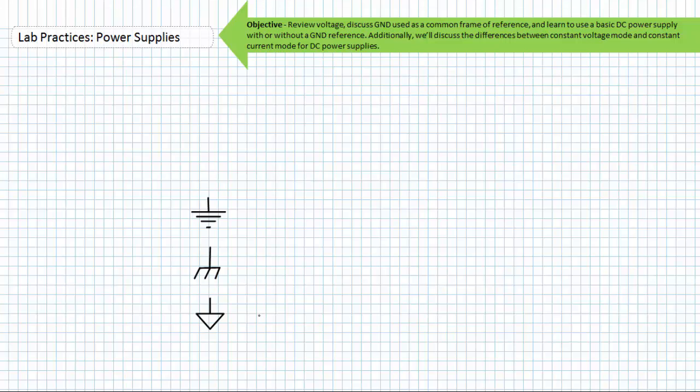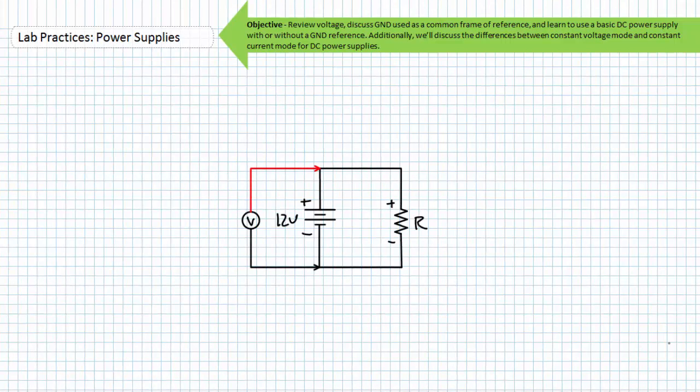In electronic circuit theory, a ground is usually idealized as an infinite source or sink for charge, which can absorb or supply an unlimited amount of current without changing its potential. This ideal scenario breaks down when a ground connection has significant resistance and this approximation of zero potential is no longer valid. An electrical circuit can exist with or without a ground reference.